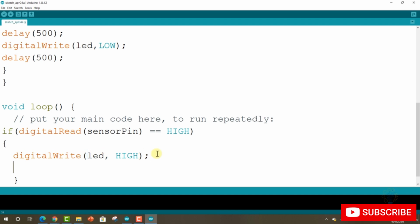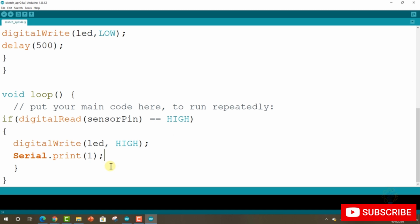And we need to send something to the serial print. So serial.print, you can send data, or you can simply send 1 or 2, or you can send sensor is on or motion is detected. This will tell the host computer that we detected motion. Now, after this, we need to sleep for 1 second or 2 seconds. So add a delay of 1 second.